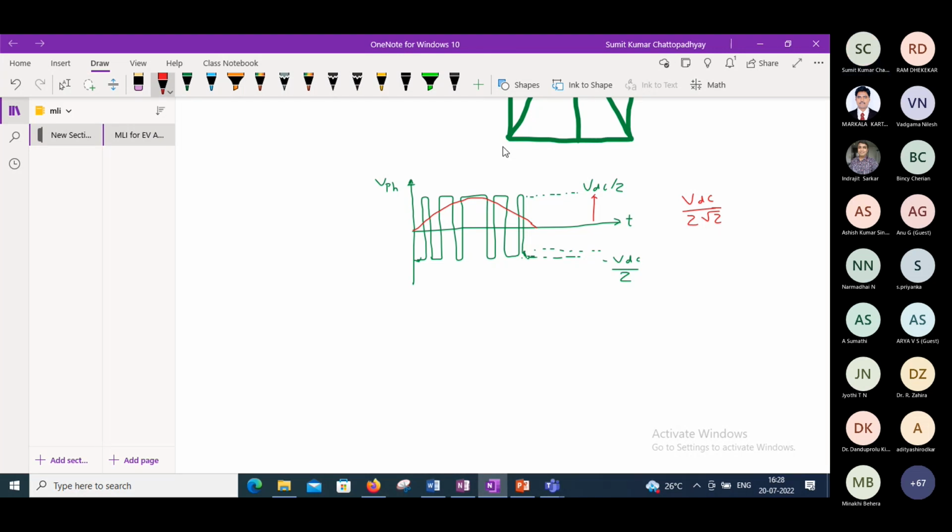Moreover, depending on the frequency, the size of the local hysteresis loop, that is, depending on the ripple current on top of the ideal current or harmonic current component, the local hysteresis loop's area will determine the effect on its eddy current losses. But in a nutshell, we can definitely say there will be a significant difference in the specific core loss, that's the core loss per kg.